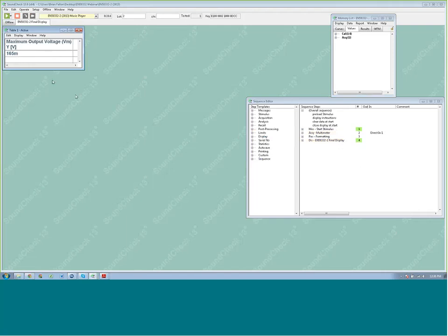And we get our final result here at the end. So we just monitored the level coming in, and there's no weighting curves being applied here or anything. It's just straight up voltage. So it's saying maximum output voltage. Now that is RMS that we're looking at. It's not peak. So the max RMS level here was 165 millivolts. So that's our information that we need to then take for reporting and figuring out what needs to be done